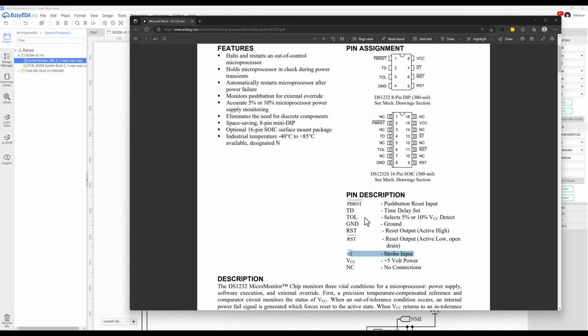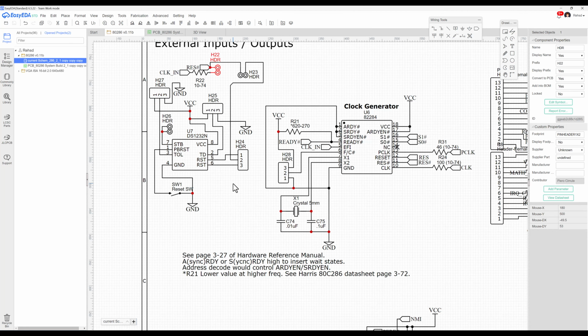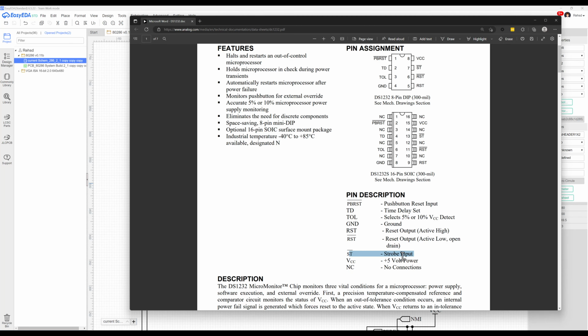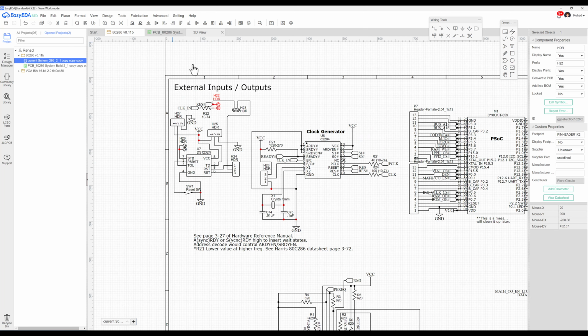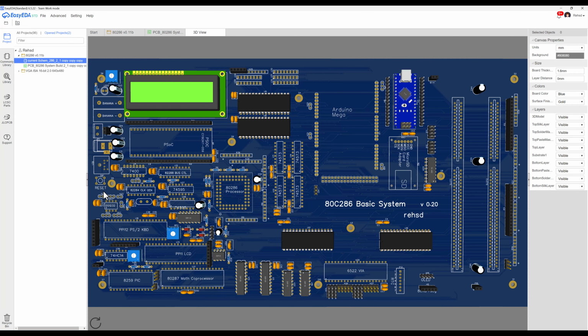So I don't know how I'm going to use all those exactly in my configuration, so I'm giving myself some flexibility with these pins. So if I go look at this strobe input, you'll just see that I'm giving it a pair of pins here, and I can later experiment. Do I tie it to A0 or A10 or something else in my system that makes sense to keep this watchdog continually updated so that it doesn't reset unless it needs to? That's been added, and that is this addition here along with the button here and all of these extra pins connecting to that so that I can experiment.